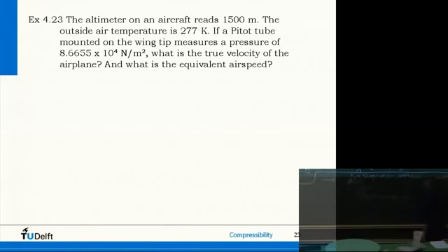Well, this tube doesn't fill up. The flow goes just past it, and inside the tube it is felt, the pressure locally at that point. So you have the static pressure and the total pressure, and this differential pressure gauge measures differences, right? So you have information on P0 minus P static at that location.